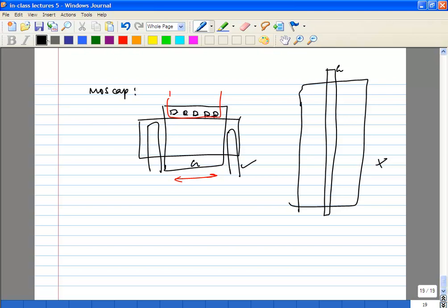What else? The other thing, transistors. We already looked at splitting transistors into fingers and so on, but one thing to remember is that splitting into fingers can also be useful. Let's say even the capacitor, right? Instead of having one large capacitor or one large transistor, splitting into more devices can help in other ways. Take the case of the bias. Bias transistors are typically much larger than the signal transistor. It helps you to actually